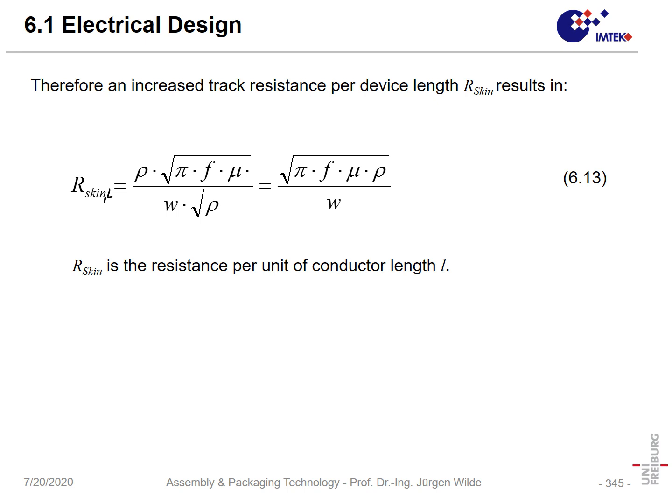Then the skin depth is only 1/10 of the skin depth in a non-magnetic material. In that way, skin effect already has an effect in conductors of large cross sections like high voltage power lines, and that's one of the reasons why people now tend to install high voltage power lines which carry direct current and not alternating current anymore.